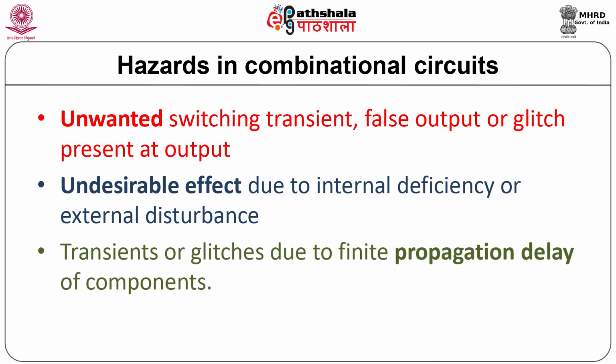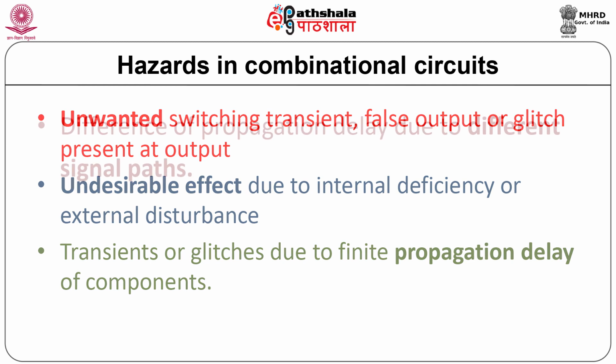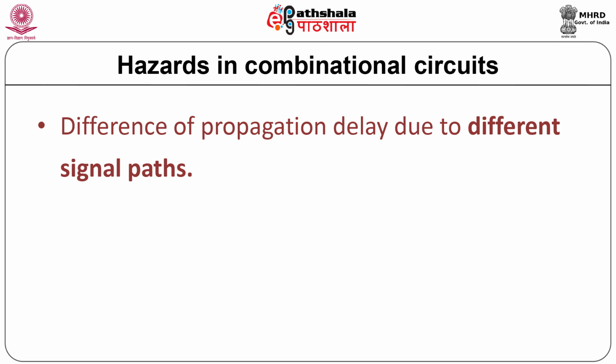In combinational circuits, these transients or glitches are due to finite propagation delay of the components along the different paths within the network. The difference in propagation delays corresponding to different signal paths results in hazards.